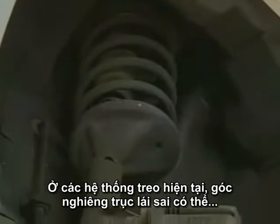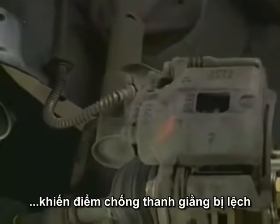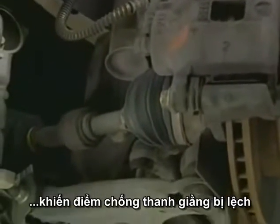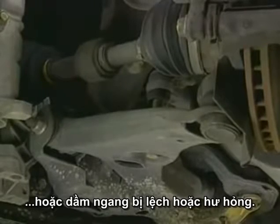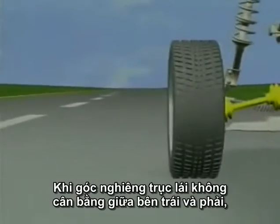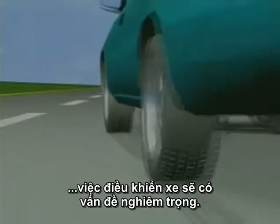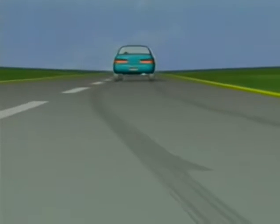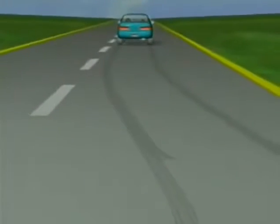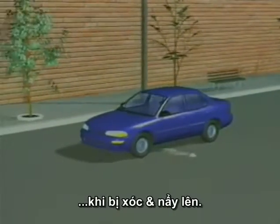On McPherson strut suspension systems, an incorrect SAI angle may indicate that the upper strut mount is out of position, or that the lower control arm is bent, or that the crossmember has shifted or is damaged. When SAI angles are unequal on the left and right sides, serious handling concerns can occur. These problems include excessive torque steer, steering pull during stops, or bump steer that pulls the car to one side during suspension jounce and rebound.